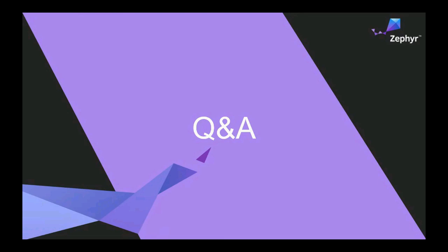There's a question by Eli, I think, is that a good reference for porting a board? We have a porting guide that I'm going to link to in a minute. There we go. So that's a board porting guide. You can use that as a starting point, but what I recommend is that you take whatever's closest to your board that's already supported in Zephyr, copy that folder and start modifying. But using the board porting guide certainly helps.